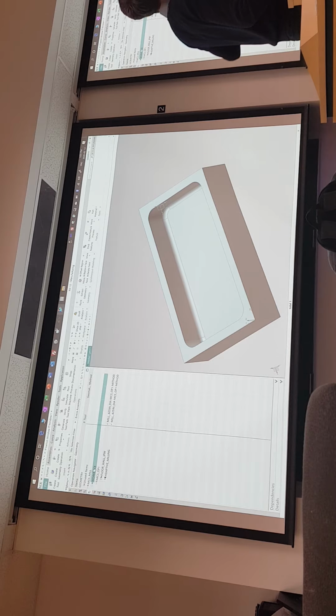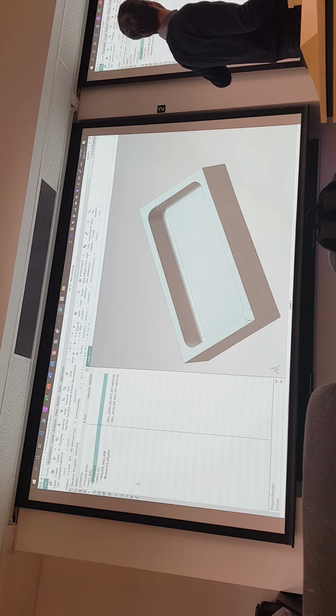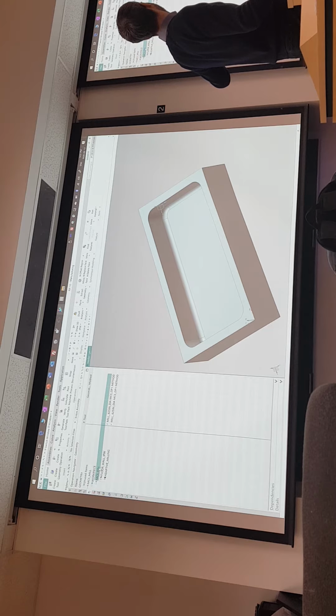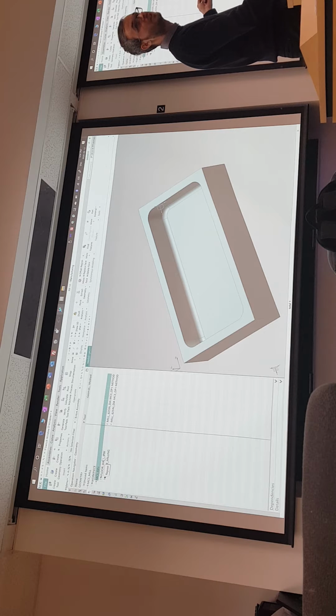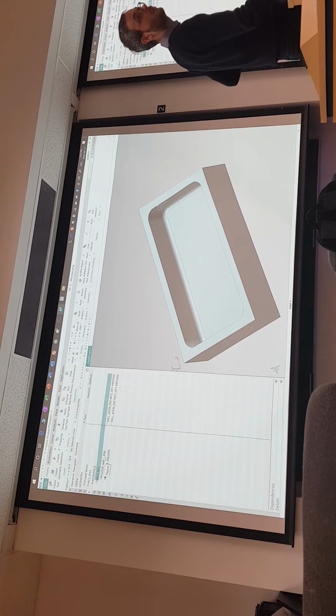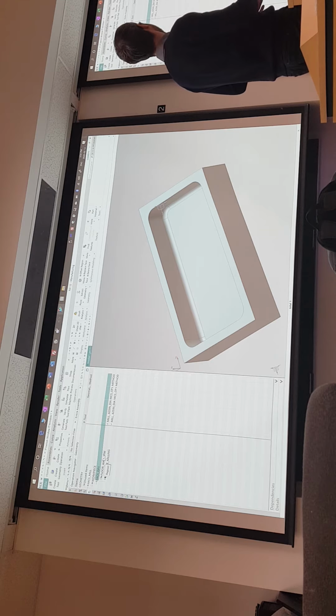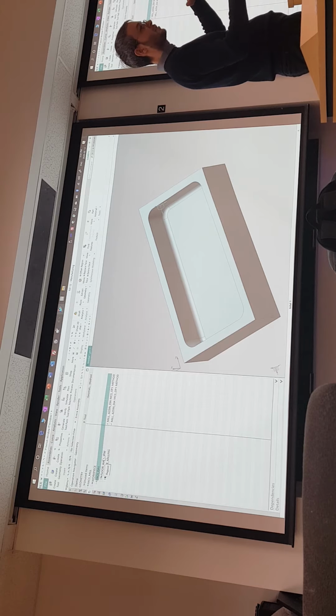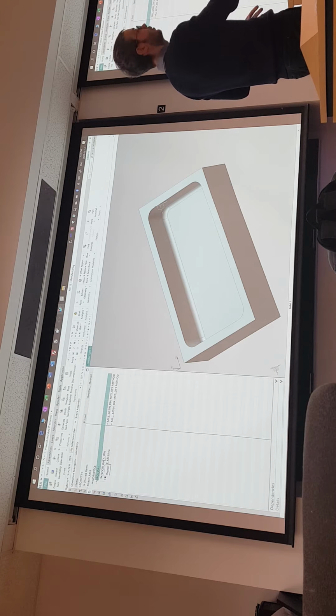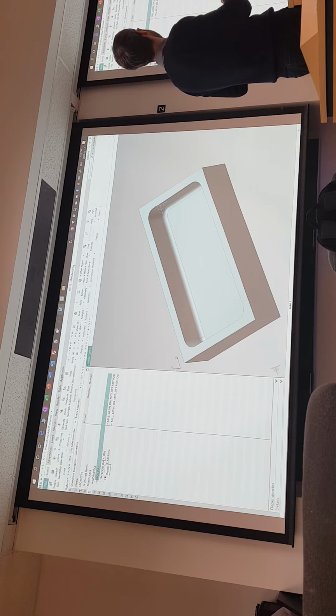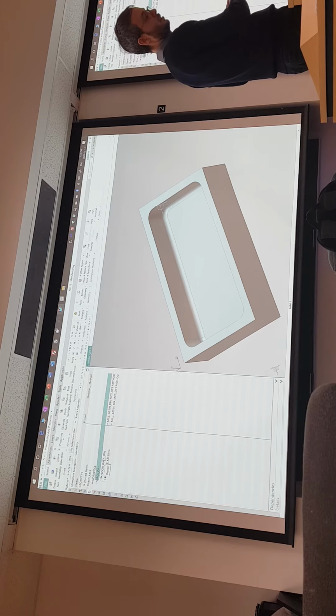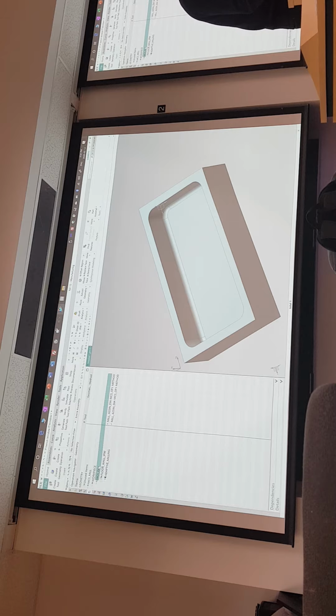So once you've specified the workpiece, then I like to specify the work coordinate that I use for that operation. And with the workpiece, you can have multiple operations. You can work on the top, you can work on the bottom. You just have to flip the axis and your tool axis. But your tool axis will automatically be related to the coordinate you use. So in this case, I said operation 1, and you can add any coordinate system.